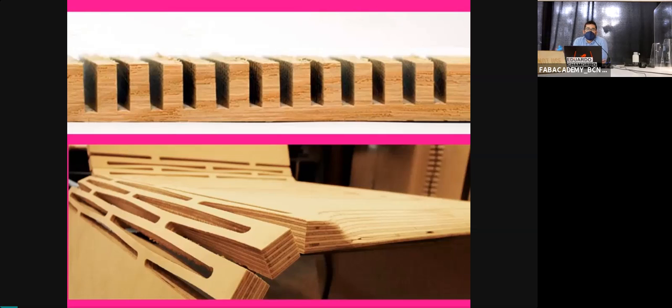One of the biggest differences between CNC milling and laser cut is the depth of cut. In a laser cut, it's really difficult to control the total depth of material that you are cutting. When we do an engraving, this kind of superficial scratching or burning with the laser cut, imagine that I put the laser here and engrave my picture, you are cutting material away. But it's difficult to control the total amount of material that you are eating or destroying. In a CNC mill, you can control exactly how much you go inside the material, the total depth. So if you have, for example, a 20 millimeter board, you can cut exactly 15 millimeters and leave just 5 millimeters of leftover material.